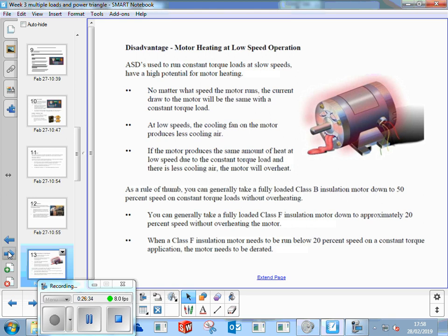It's because the cooling air isn't there. Yeah, they'll provide you with a higher class of insulation then. It might do, because that's what it's talking about, is derating it. Saying, you know, we got to rate this power of this motor down and the current rating is down.